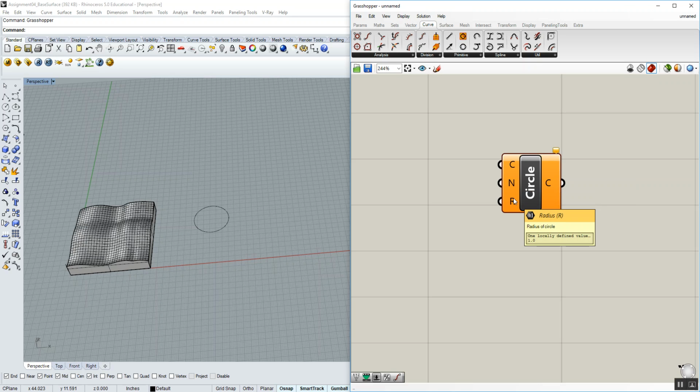You'll see here that the radius already has a value of 1 stored in it. You'll see here that the plane is already set to 0, 0, 1, meaning the 1 is in the z-axis, so it's going to lay down on the xy. If that said 0, 1, 0, it would be on the xz axis, and so on. The 1 is the direction that is normal to, or perpendicular to. So in this case, the 1 is in the z, meaning it's on the xy plane.